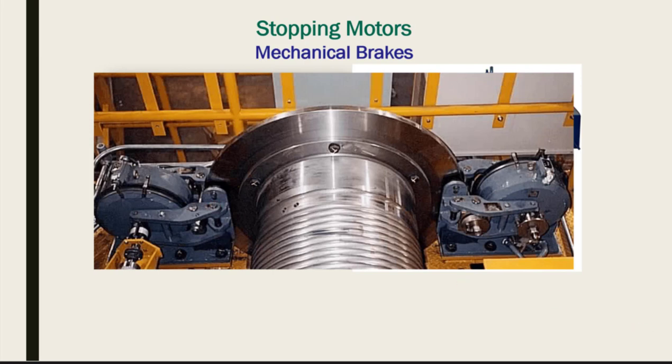One of the problems, however, with using mechanical brakes is that they wear. You have to change the shoes periodically. They also create dust from the wear of the shoes. They create heat as this friction builds into heat, and it heats the ambient air, causes the air to warm up. So then you have to pay for air conditioning or things like that if the temperature gets too high. And there's wear. These things just wear out, so it needs replacement. That's downtime while maintenance is done to replace brakes. So mechanical brakes are effective and they're reasonably inexpensive, but there's definitely some problems in using them.